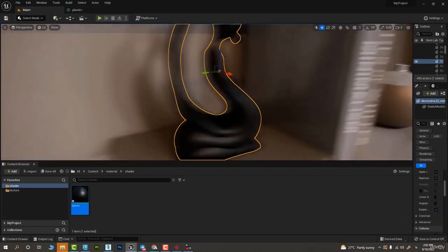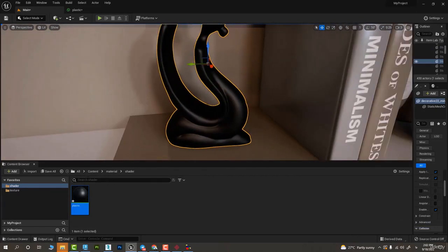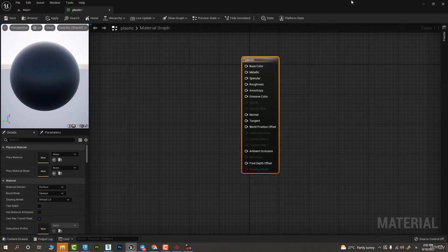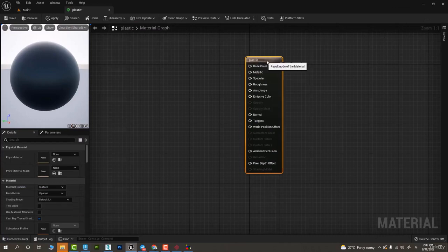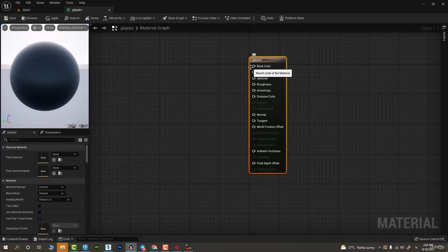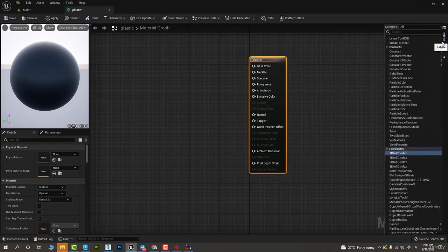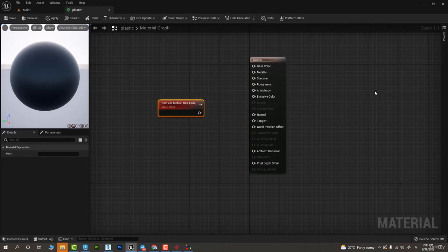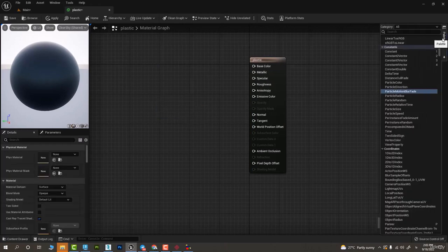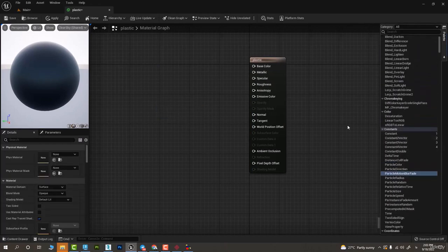It's just a simple black base color with nothing for our material. So if we go back to the slate, if, for example, we want to start by using a very simple black and white color for our base color, we can go to this right panel that we talked about and add a node. For example, let me just find the one. It's called constant. So if you want to use a black and white color, all you have to do is just drag this constant node.